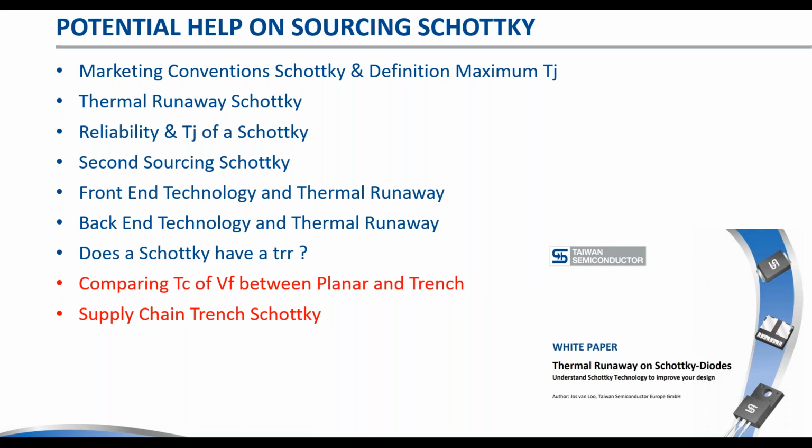The two points I highlighted here: first, the temperature coefficient of VF between planar and trench Schottky. In a lot of searches, if we compare the initial VF at 25 degrees C, the trench Schottky will always look much better. But planar Schottkys have a much better temperature coefficient in general.